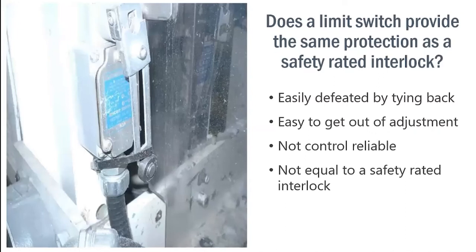So some of the things we see with interlocks: people say, oh yeah, I've got an interlock on the machine. Well, you look at it, and it's one of these simple proximity switches. They do not provide the same level of control as a safety rated interlock. They're easy to defeat. We can see here, this one's tied back with a zip tie.